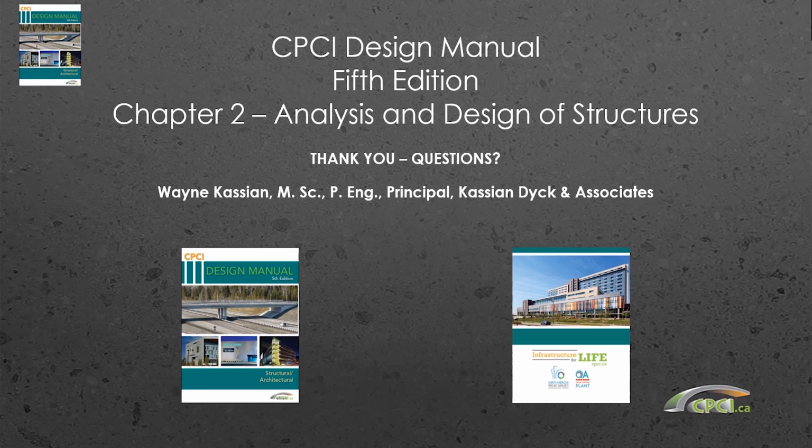I had another question, where I was talking about the concrete diaphragm topping over the hollow core having a different shear limit compared to cast-in-place, and the person asked, if you decide to use the cast-in-place equation rather than the precast one, is that not against the code?